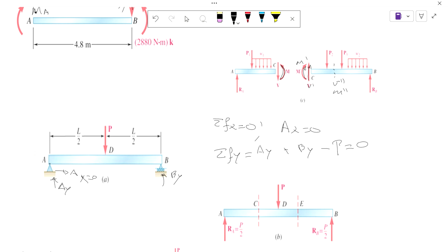I'm picturing kind of like an 18-wheeler trailer carrying some box, some heavy duty equipment at the middle. The fixed point is actually where the axis would be for the road, or for the tire, and this roller point will be the hinge where you would connect it to the truck, and you'll see some type of deformation like this that is uniform. I'm exaggerating, right? But this is how you expect it to deform. Okay, it's symmetrical from this point to L half and L half.